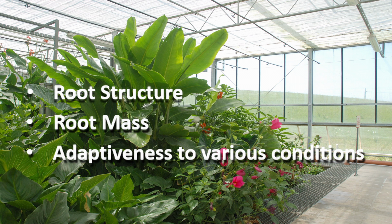Greenhouses are industrial buildings that are manufactured in large quantities, actually usually in hectares. So as such, it's a very inexpensive type of building, and they come with various features all pre-installed, temperature control and shading and misting equipment, and even wind speedometers that automatically close the windows of the greenhouses. Again, the role of the greenhouse is to provide a minimum 6 to 8 degrees ambient temperature.